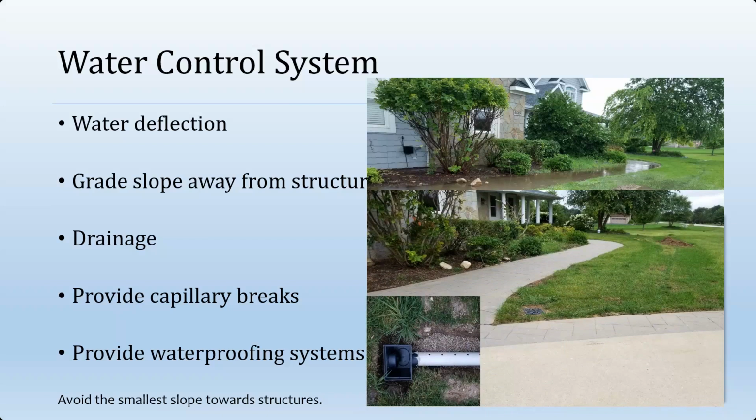But instead of using that 4-inch ABS pipe, I elected to use the 4-inch SDR 35 pipe that's slotted on only 1/3 of the circumference. The reason being is that I wanted to be able to capture that water and get it away from the structure. I don't really care for that 4-inch corrugated stuff because it's slotted on 360 degrees of its circumference, and that would just drop a lot of the water right there. Yes, granted, some of the water does find its way out, but for the most efficient result, I used the 4-inch SDR 35 thin wall. And yes, it's more work. You have to dope the elbows and 90s.